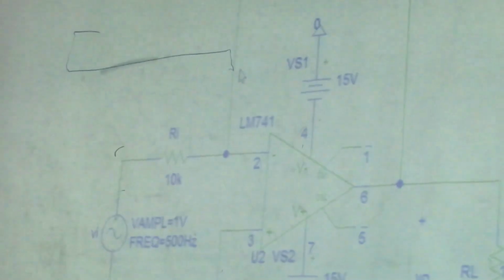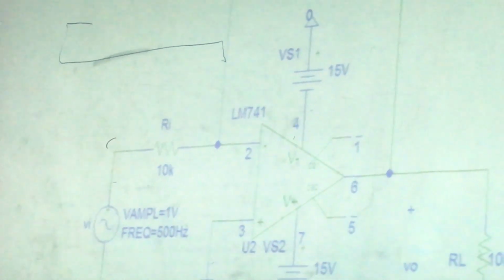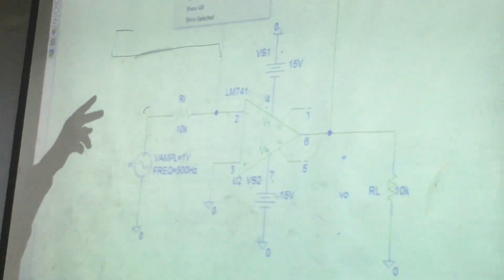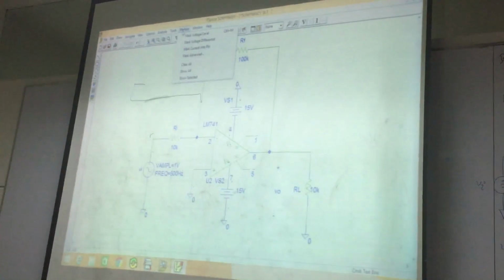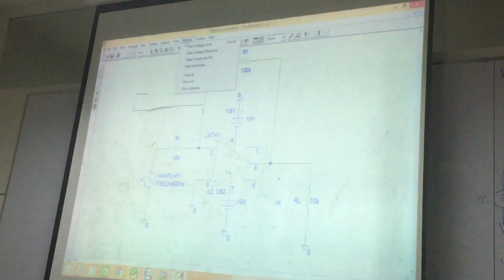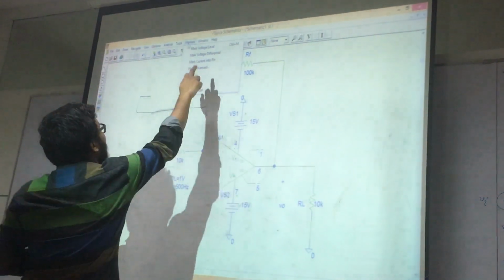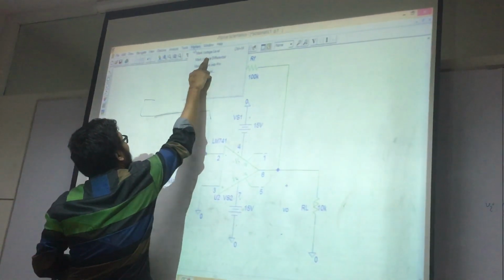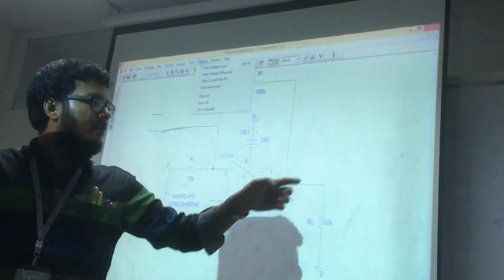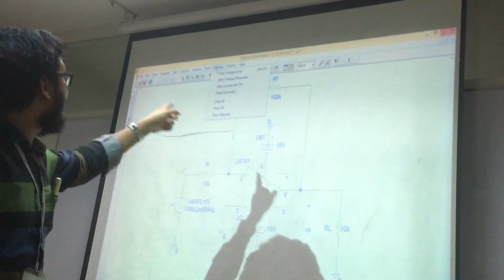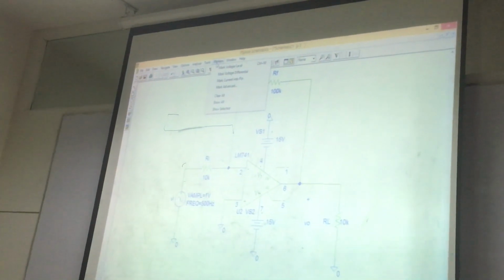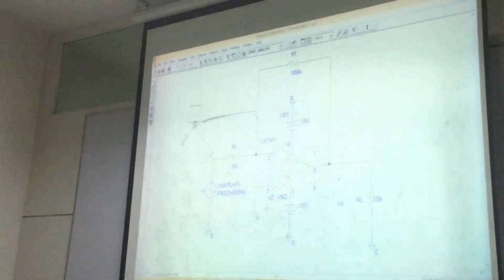Using markers, voltage markers. Here, markers. First two are voltage, then number 3 is current. This guy is a nodal marker and that guy is a non-nodal marker. Because these two voltages are nodal voltages, we're going to use the first marker. Mark voltage on level. This one.